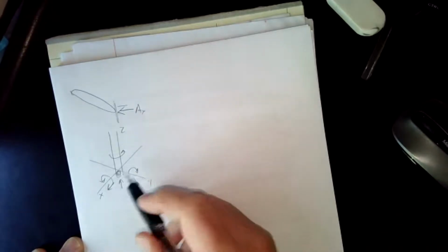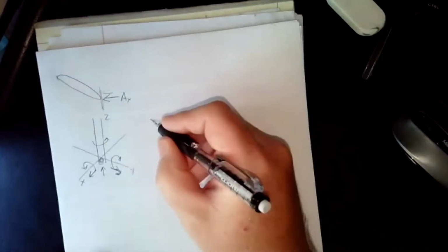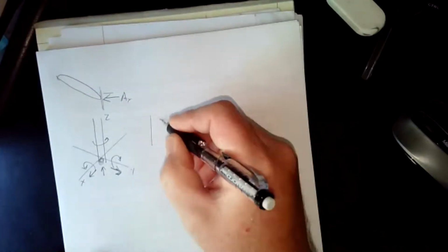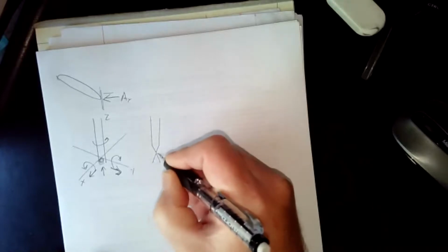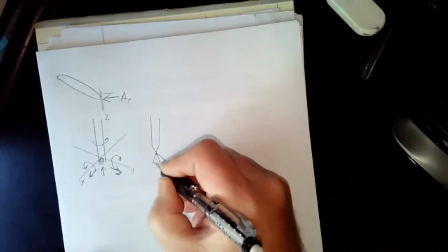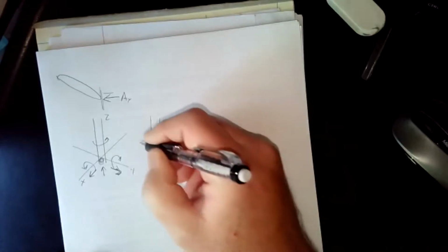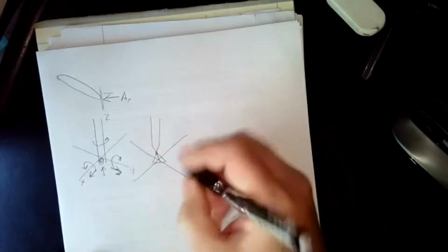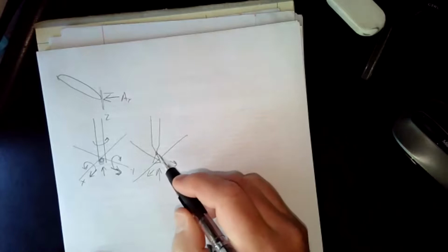So you have 6 unknowns in this case. That's the most that you'll see, or most of the time you'll see something like this. It's called a ball and socket joint. It'll look something like this, where it's connected by ball and socket. In 3D, you'd have just a force that way, a force that way, and a force that way. So 3 forces, but it can't support a moment because it's free to rotate.